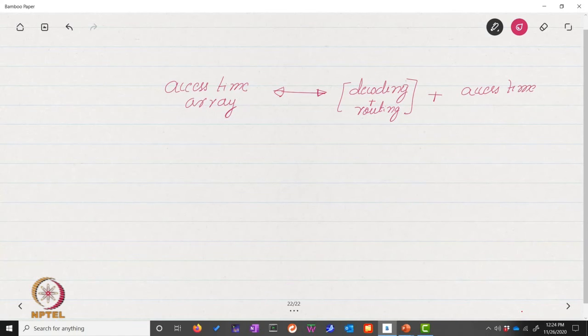So this is essentially the trade-off that we are looking at. We cannot have too many subarrays, like we cannot have 100 subarrays, right? Maybe we can't have 1,000. Number one, because this overhead will become too much. And number two is that now a block will be split across subarrays, so we need to read multiple subarrays, right? Because each one of them would be containing a part of a block, right?